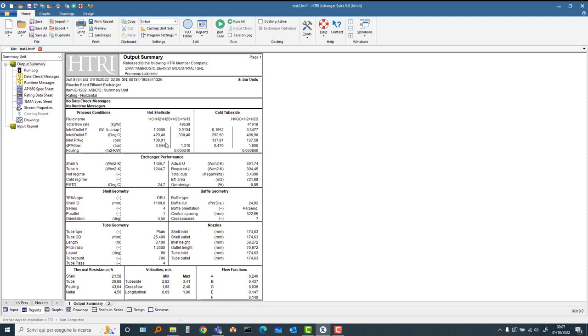On the shell side also there is space, if you like, but what is the deciding coefficient? The tube side coefficient is lower than the shell side. It's 1200 against 1400. So the idea is to increase the number of passes. So let's check one more thing. The tube layout is really the tube layout that we have seen before.